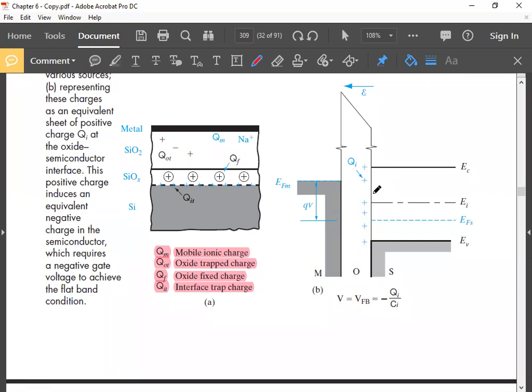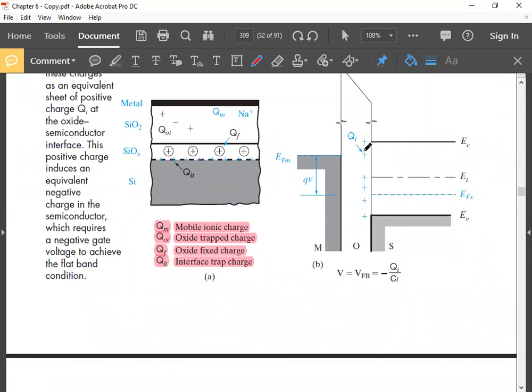When the desired thickness is achieved, the supply of oxygen is terminated. Oxygen was diffusing and reacting with silicon. Here at this interface layer, some silicon atoms were in the process of reacting with oxygen. Those silicon atoms became ionic and were expecting oxygen atoms, but suddenly the oxygen supply is terminated. So there will be some dangling bonds, meaning unsatisfied bonds.